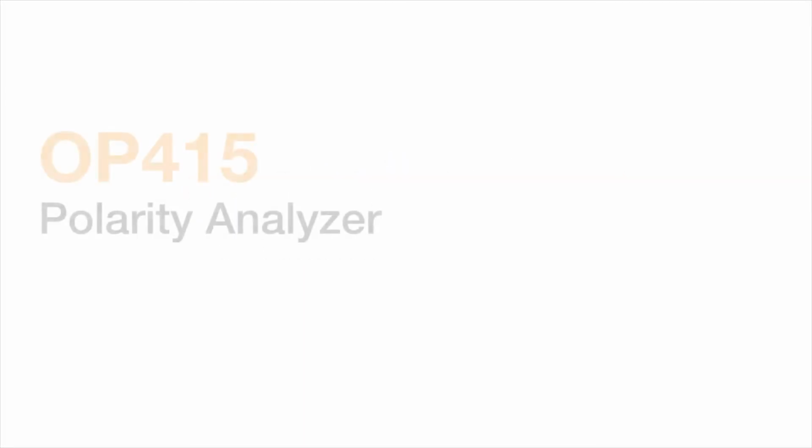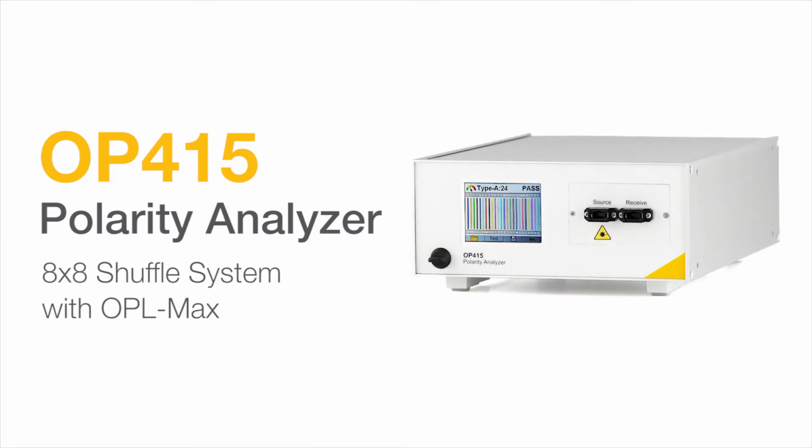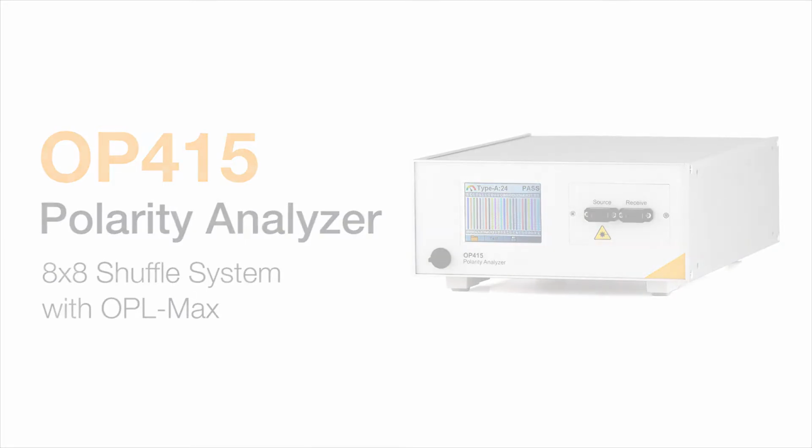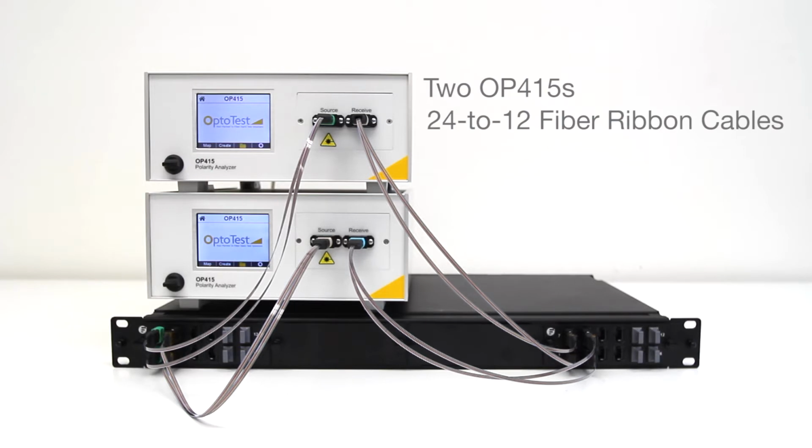In this video, we will test the polarity of an 8x8 shuffle system using the OP415 Polarity Analyzer and OPL-Max. For this test, we will use two OP415s to show how multiple units can be used to test complex systems. The cables being used split the 24 source and detector channels from each unit into 12 fiber ribbon cables that connect to the shuffle. With two units, we are able to connect to half the source ports and half the receive ports of the shuffle at once.